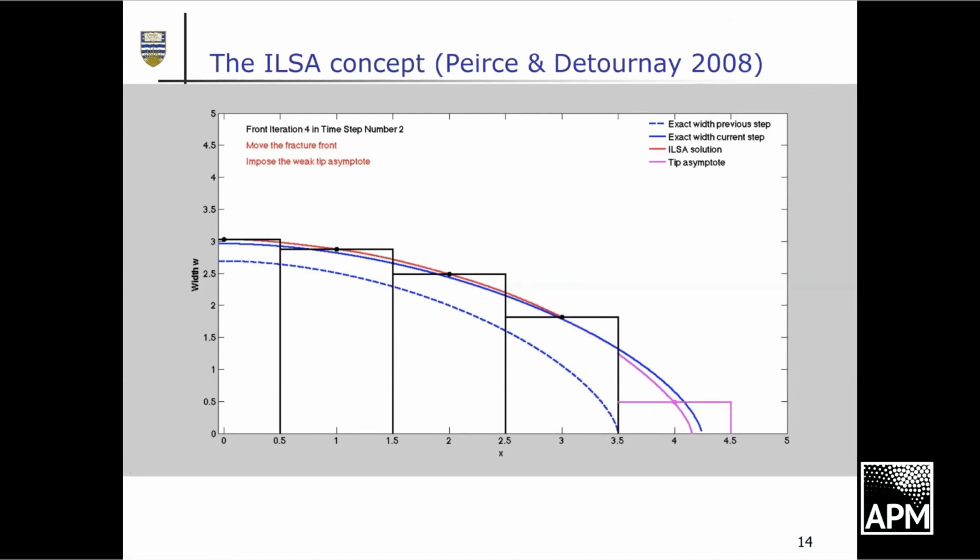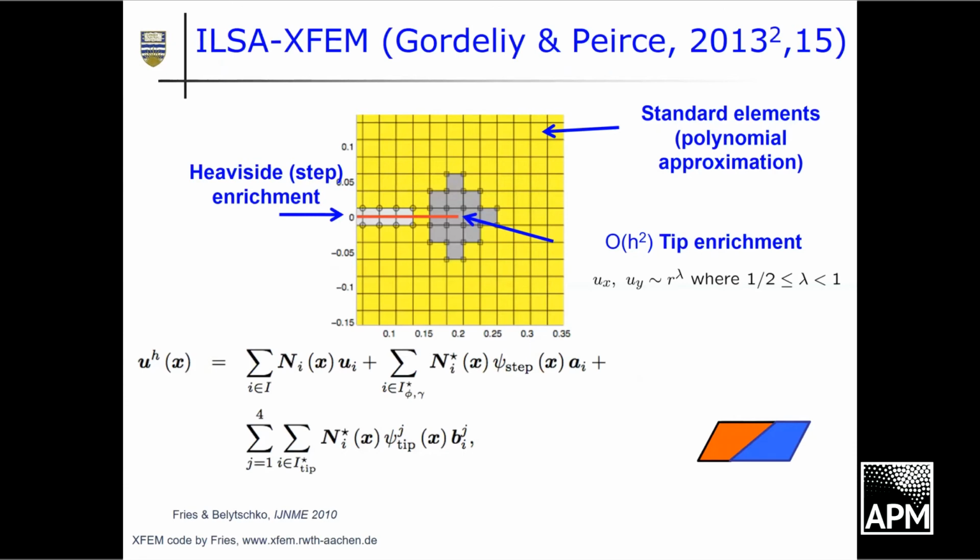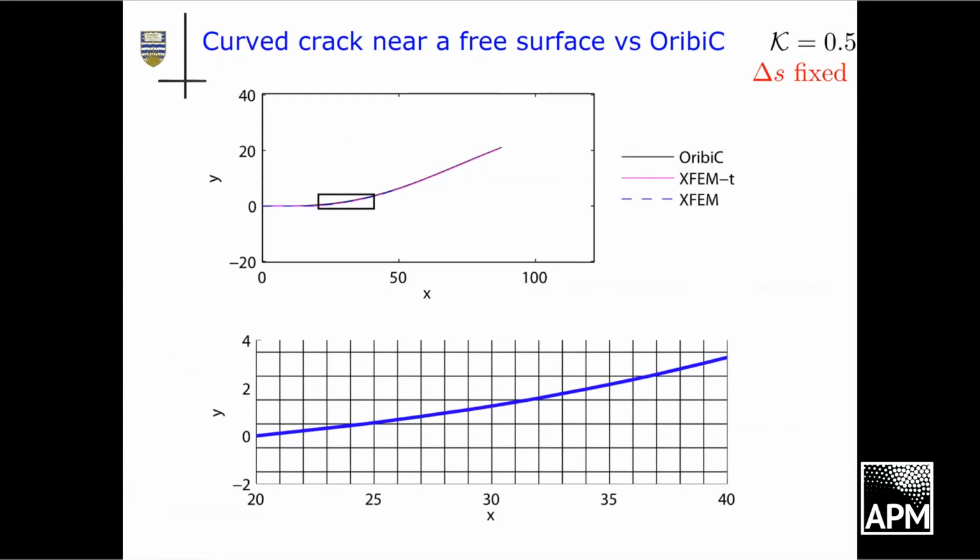Okay, so I'm not going to talk much more about that. You can extend this to the extended finite element method. Basically, you introduce these step function basis functions, and you enhance the tip with the appropriate power law that you want, and these are the enhanced basis functions. And I'm just going to show you some results. This was work with Lisa Gordelli. This was a fracture near a free surface, and it's curving, and we managed to match a boundary integral code.